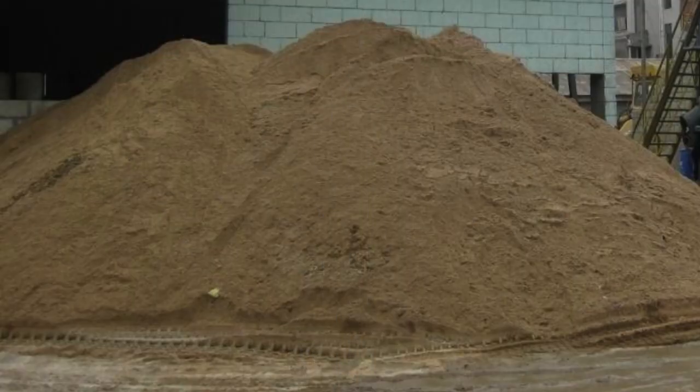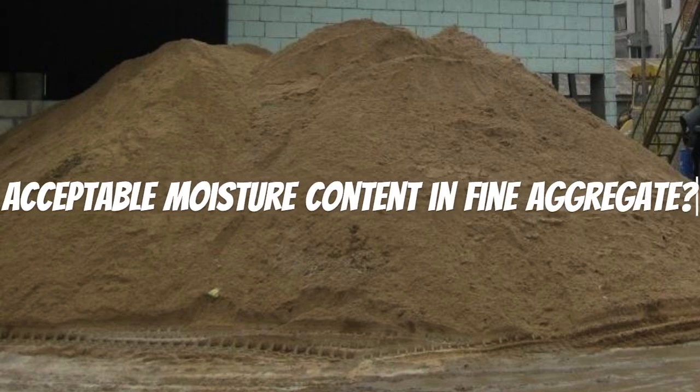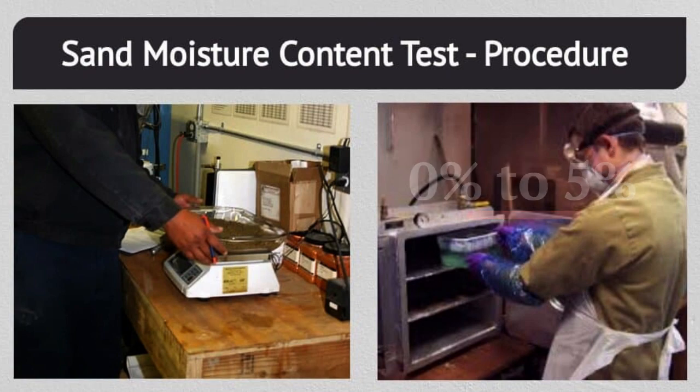Question 5. What is the acceptable moisture content in fine aggregate for the concrete mix? Answer. It should be between 0% to 5%. For fine aggregate, if the moisture content is more than 5%, it is not preferred to use.